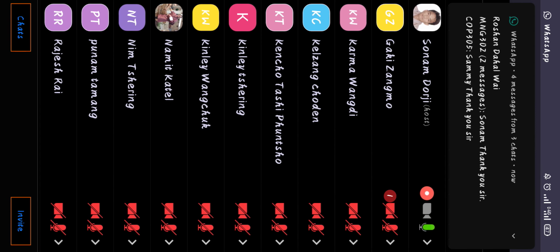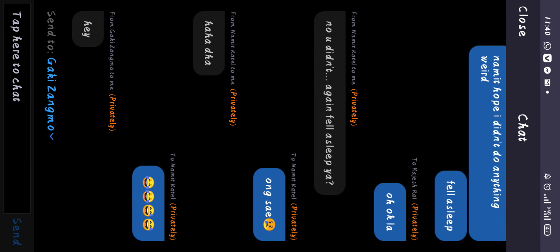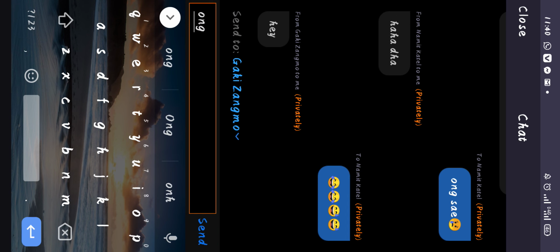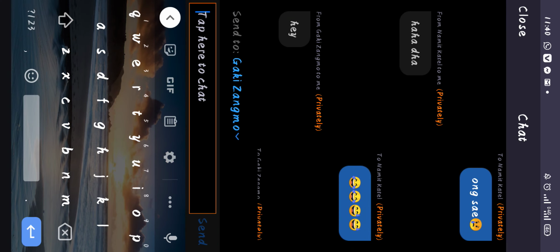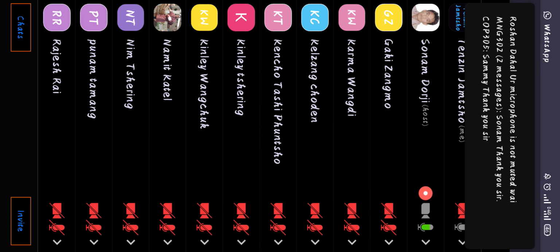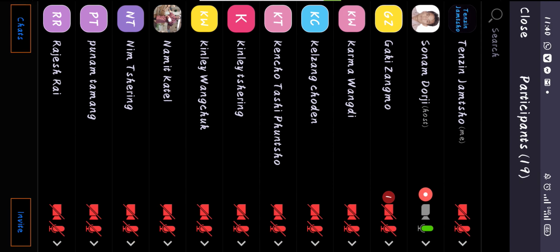The first one is TSC and this one is TCR, as already mentioned, and this one is used for filtering, because when we use TCR it generates harmonics, so we have to filter the harmonics. So we use a filter.